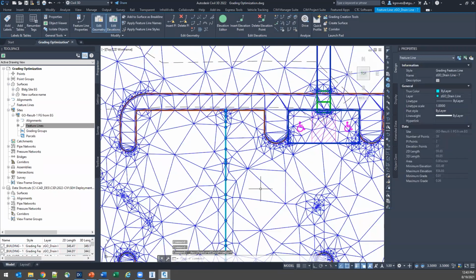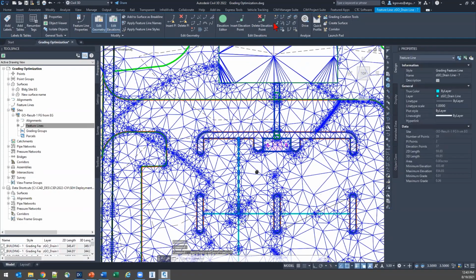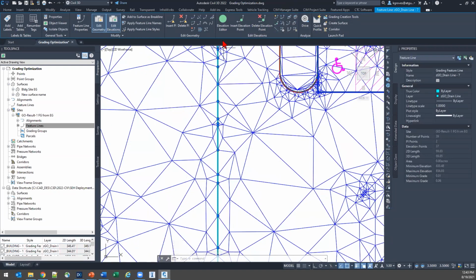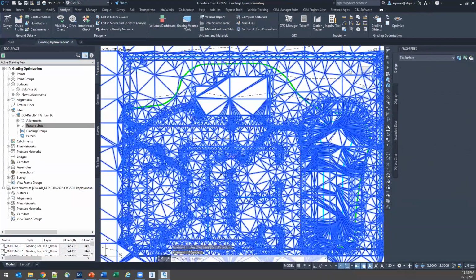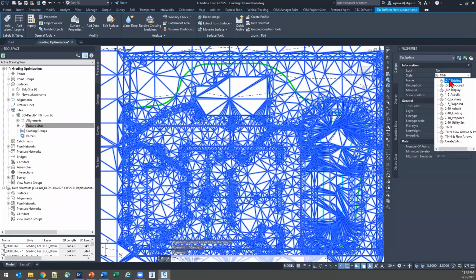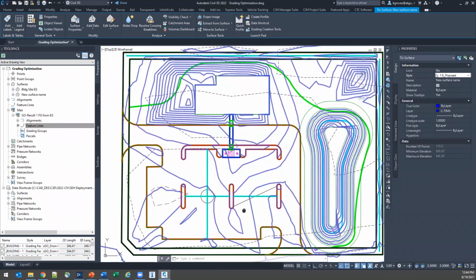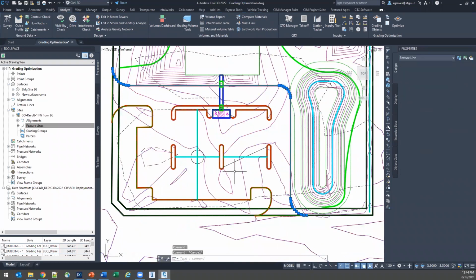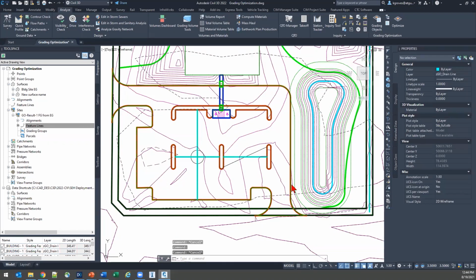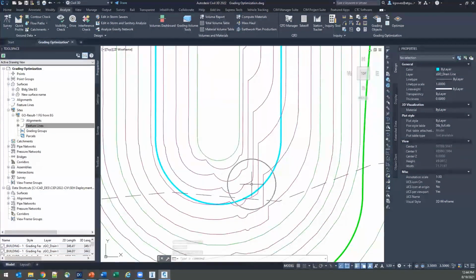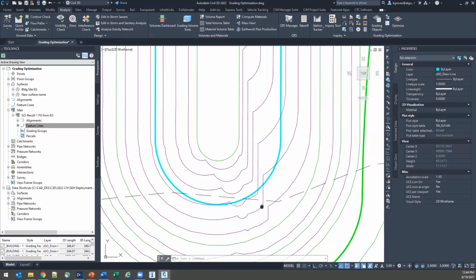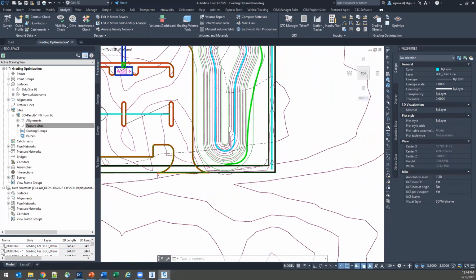So this is going to be really rigid data. I am not going to want to come in here with my quick elevation editor and pop through all that stuff. So what I'm going to recommend for this resultant surface, this is a really great way to get yourself very quickly to a small number of potential design options. You can get there by changing some of the constraints of your various grading objects, of your various grading zones. But this weird cut right here is going to need some management. I'm going to want to redo that.